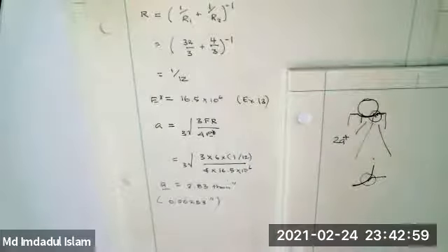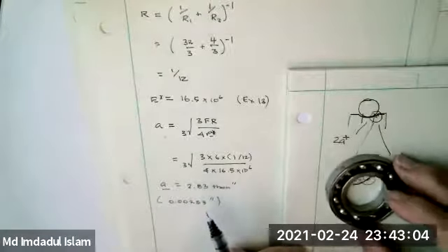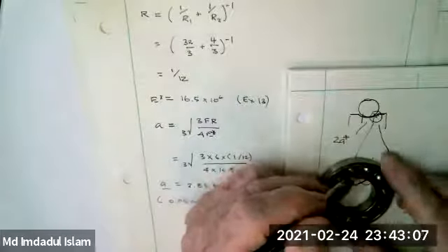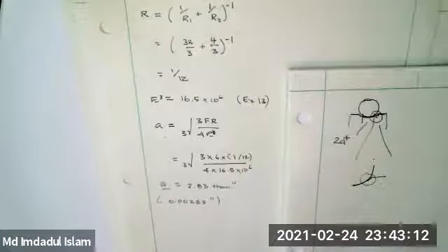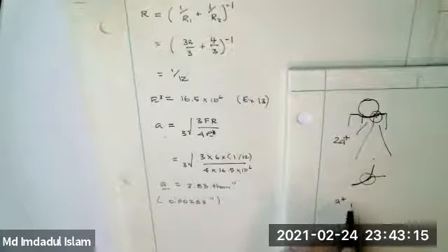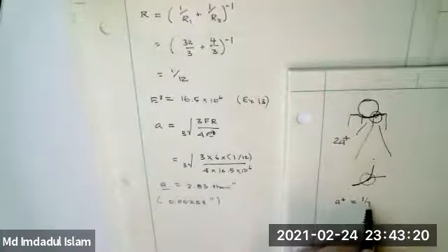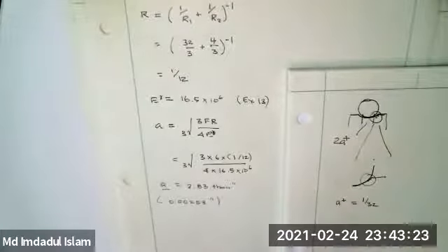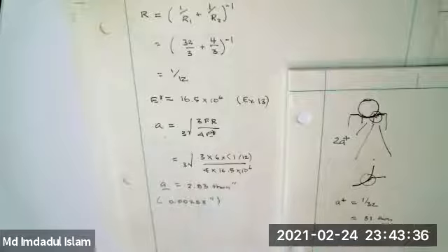And so there is some dimension here of the contact extent. And so I've looked at this. I got a flashlight and a magnifying glass and tried to look sideways and see what this is. And I estimated that this whole length here was about a 16th. So I have A plus as 1/32. Or if you like, 31 thou, an order of magnitude bigger in that direction.